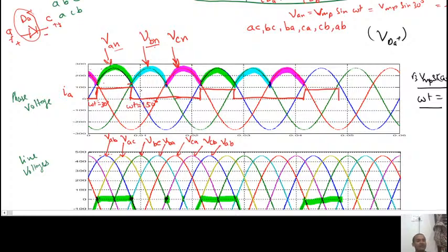Again, after finding all this source current for the constant current load, one thing you have to do is find its Fourier series analysis, and after that find the displacement power factor, the power factor, and the THD. Before that, let us find its average output voltage. What is the time period here? You can see that it's a 3 pulse rectifier, very simple to see. How will you see it? In the input wave, this is the input wave. See here.